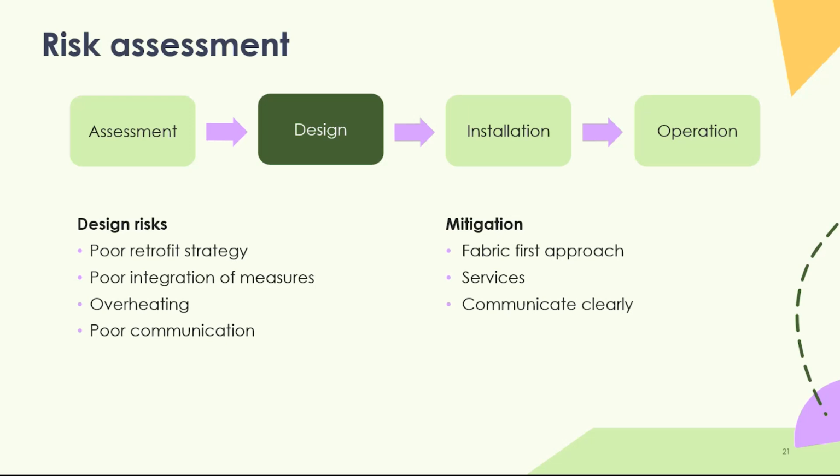And then some of the things around services that we can do. So having a proper ventilation strategy and considering supply of fresh air, extract of old air, and heat recovery as well, to make sure that you're continuously refreshing the air in that building. And then of course clear communications and a proper resident engagement strategy, clear communication, not just obviously with your residents, but also the installers as well, so that they know what you expect of them and what the residents expect of them, and that everyone's kind of working in harmony.